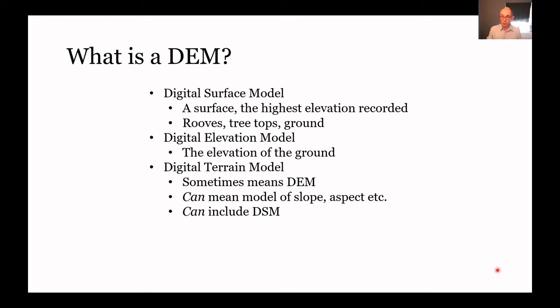A lot of the time you actually want the ground as it is rather than the things that are on the ground. The digital elevation model, this catch-all term, strictly speaking should be the elevation of the ground. What's the thing that you stand on, not any construction on top of it or anything growing on top of it. This is somewhat tricky when considering, say, erratics, large natural features that exist on the ground but maybe don't affect things like surface runoff directly if you're modeling hydrology, for example. So this could be a problem.